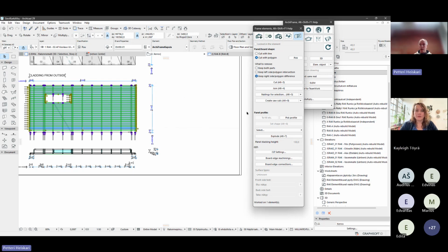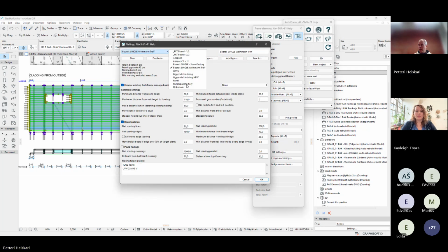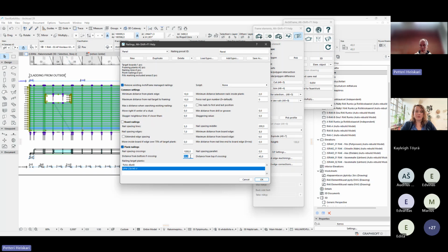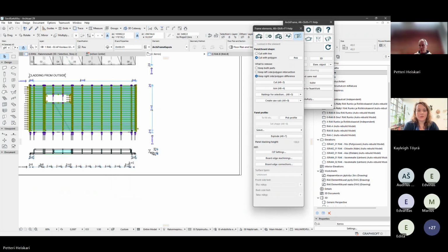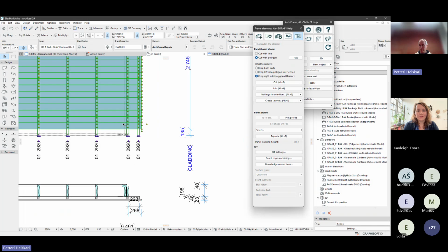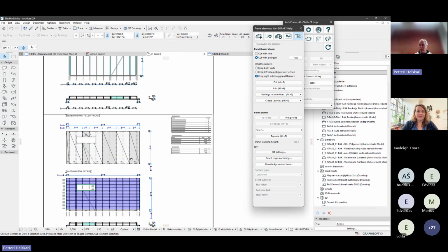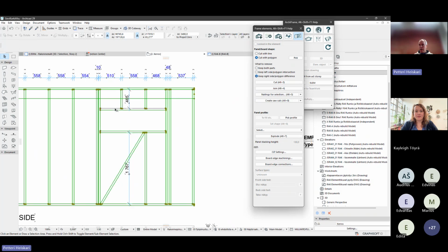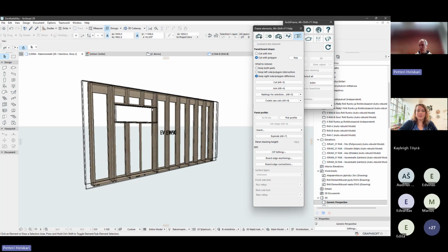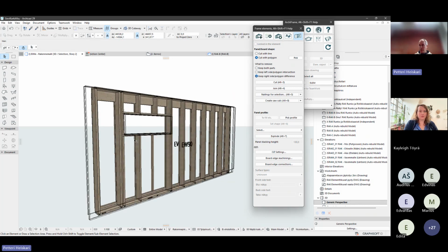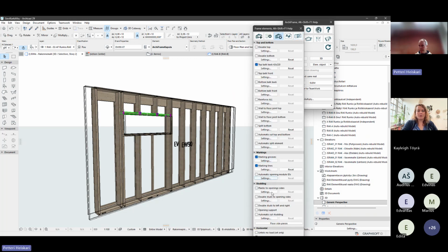Yeah. I'll quickly add the nailing since I have a nice selection here. So I use a preset here, and the important settings here are the one nail to 30 mm from the bottom and another 45 from the top. So now we got nailings to the cladding pieces. And then let's add first the lintel. And I think I added the whole beam, or let's do that in 3D so you see better. Yeah, so we have this beam already on the back side. So let's add a lintel to this one on the element tools.